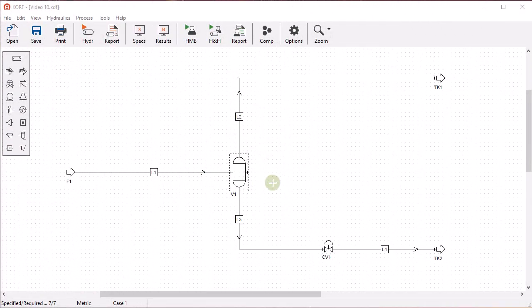Today we will show how to manage a separation vessel. Let's assume that we have a pressurized mixture of methane and water entering a vessel at 500 kilopascals, and we want to remove condensed water from the pipeline. We will receive 85,000 kilograms per hour of the mixture, and we need to deliver the recovered liquid to a nearby tank at a pressure of at least 90 kilopascals.